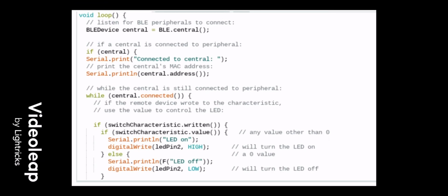We then begin the void loop, which consists of if, else, and while statements. In the main if-else loop, we set each LED to a different variable, so if it is selected on the app, the LED will light up. If a number that is not set as a variable is selected like 0, the LEDs will turn off in the order they were selected.